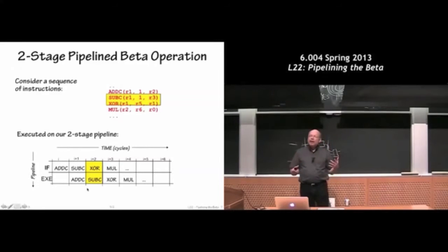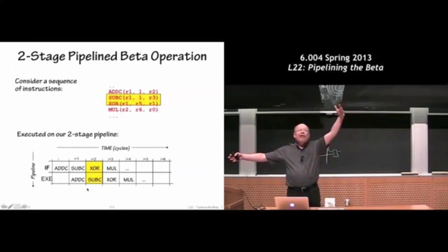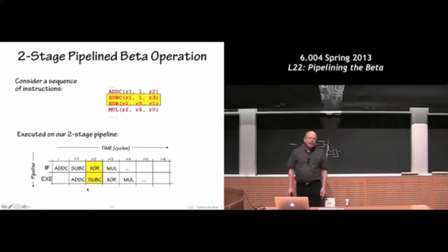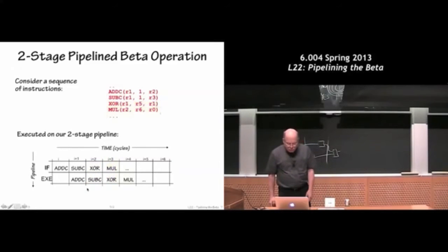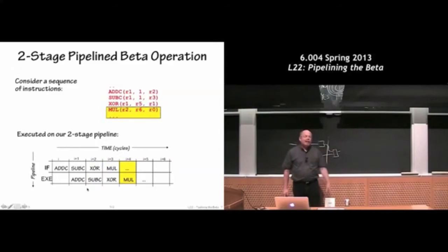And if the gods were with us, maybe our processor would run 5 times faster. If we could equally divide all the delay we need to invest in the execution of an instruction into 5 chunks, then pipelining would get us quite a speed up. We're not going to be quite that lucky, but that's the basic idea. Okay, so this all works great. Everybody's going, great, so far no problem.